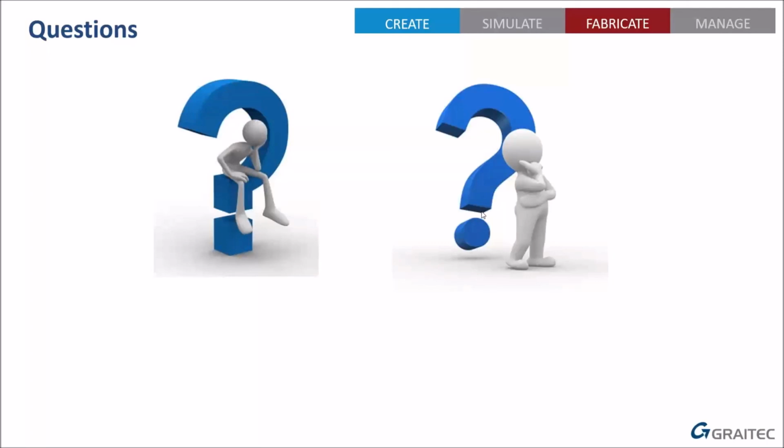If it is offset one side, we showed in the video there, when we're moving the stair around or copying the stair, use the transform elements and you can move the stair, set it to the move option. The object you want to move is just the joint box around the stair. Don't try and pick everything, just pick the joint box around the stair and then pick the right points to move it to the one side if you need to move it sideways.